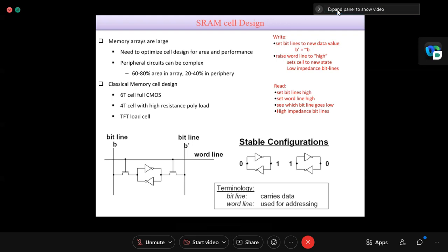Okay, so another interesting point, let's say I am asking you to design one NOT gate using a NAND gate. Anyone, please give me the answer. So design one NOT gate using a NAND gate. How can you design it? Short the inputs. Short. Okay. Yeah. So who told this one?